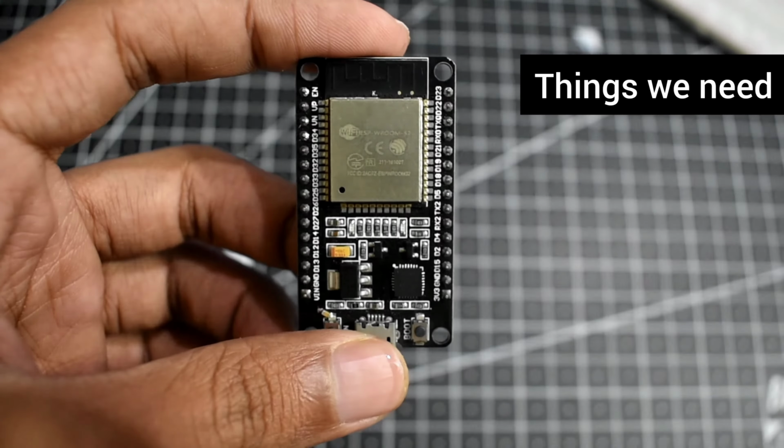Now this variable has to be replaced with this count here, and humidity has to be replaced with the data below. This was to generate random numbers, I guess. Now both my variables are there. Now I'm going to change the path to DHT_11, and it's going to be stored under temperature. So temperature, and do the same thing for humidity as well. Just replace it with DHT_11. Make sure that the spelling is the same so that it gets listed in the same path, or else you'll have two different paths. And I think that's it.